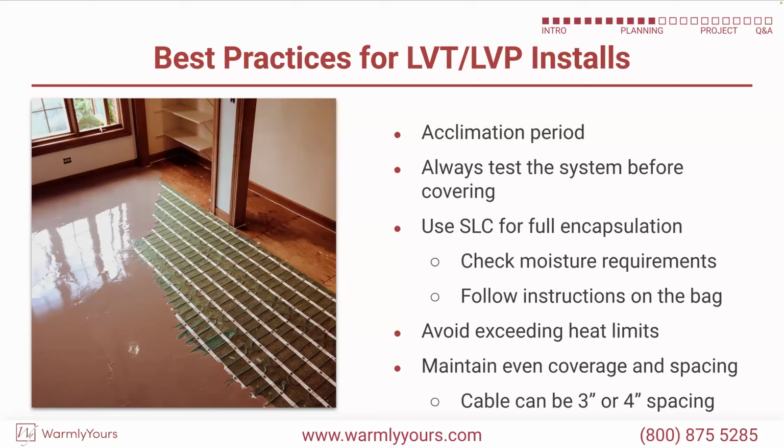And there's no way to get thin set completely flat with a trowel. So the floor I went out to, they tried to get it as flat as they could. However, the LVT was sitting on, and you see it's an irregular surface. So where it actually does hit that, it feels solid. It's a nice solid step. But where that thin set curls down now is a hollow spot, and it's hollow, good, hollow, good, hollow, hollow. So the floor was awful. It sounded terrible. Brand new floor. So they had to do it again. Don't use thin set when self-leveling is required.